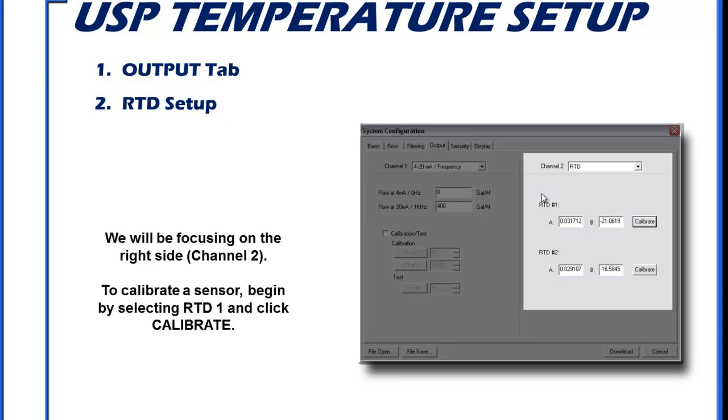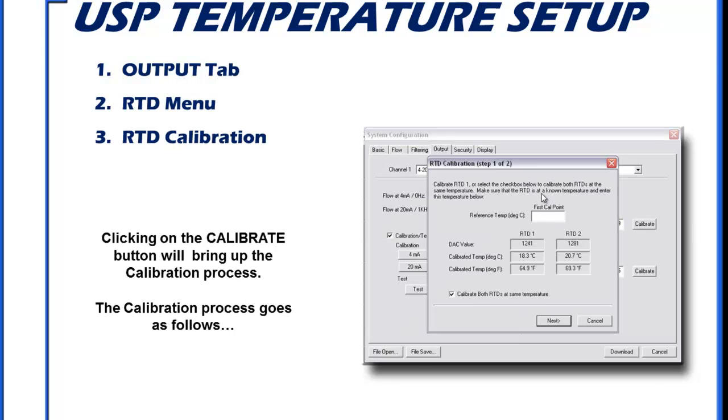For those who need to use their own temperature sensors, 3-wire platinum RTDs, or a wetted sensor that they're providing, you can still use this transmitter as long as you have the energy option, and you can program it yourself for your particular sensors. When you buy it directly from us with our temperature sensors, it is plug and play. No calibration or adjustments required. But we're showing you it does have the flexibility to program it.